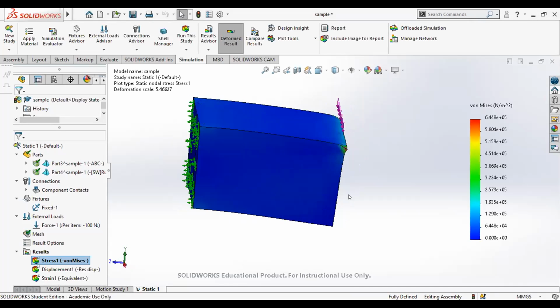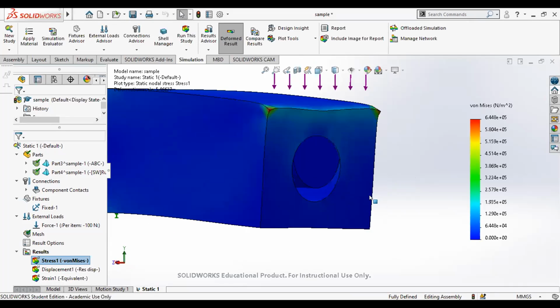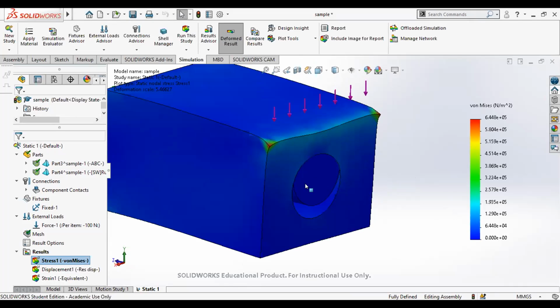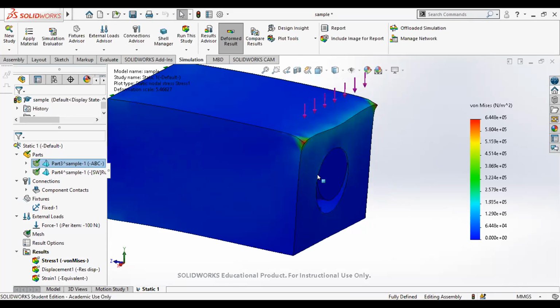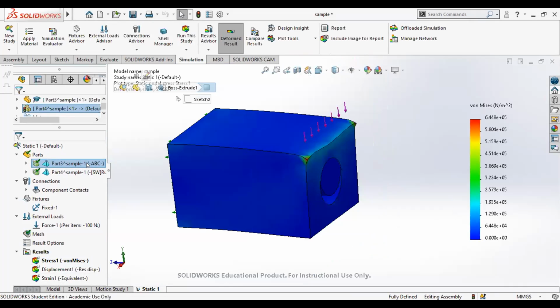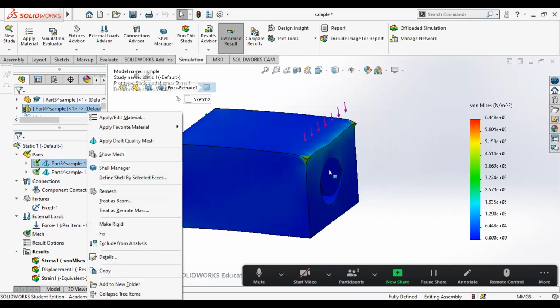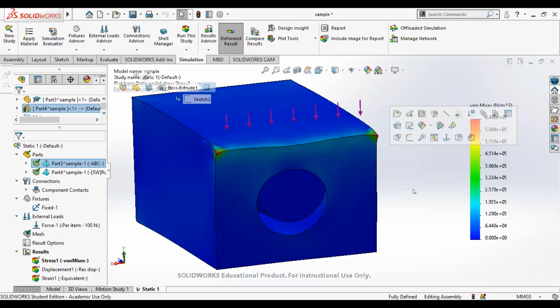You can see, because you have two materials, the two materials have different elastic moduli, so they will deform differently. You see the outer case here, where I put a rubber, it is softer, and I put a harder material inside. So you can see the outer deforms more than the inner here. The way they deform is different. So the result actually shows you the difference. The force is from the top, right?